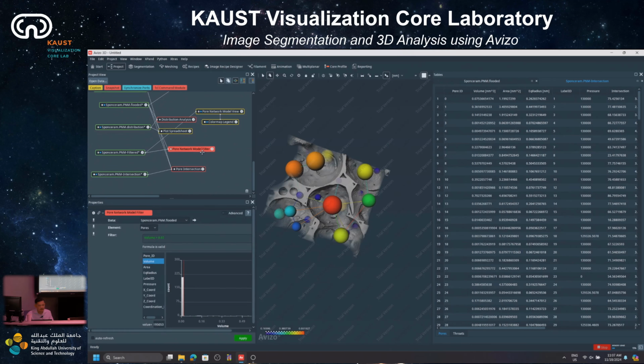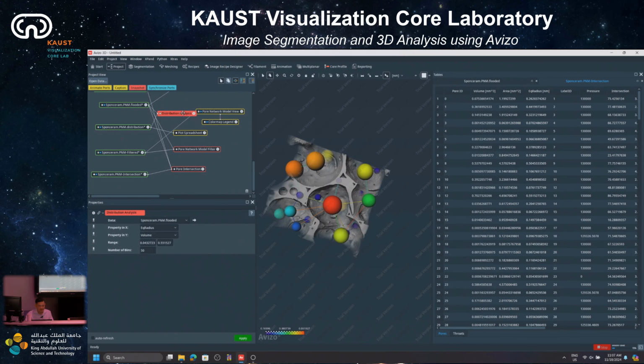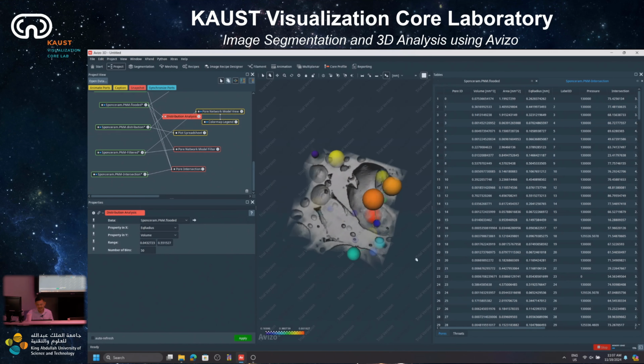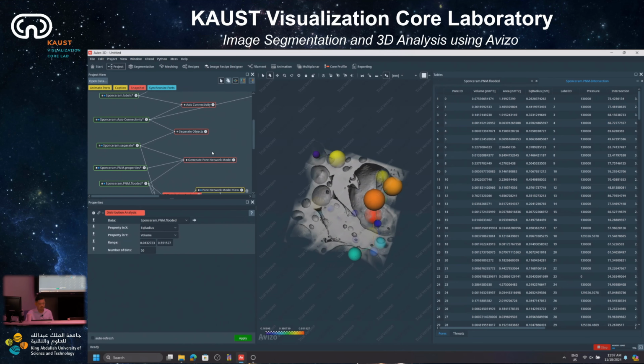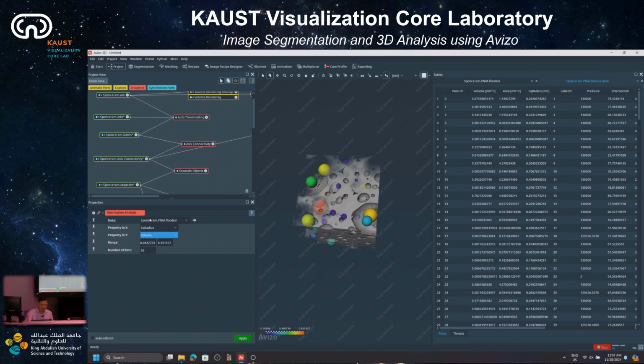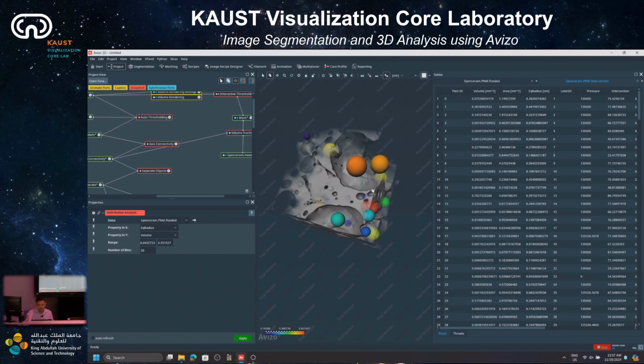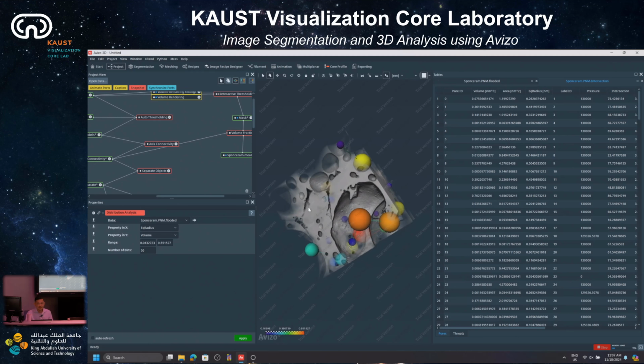Yeah, that's pretty much the pore network model. So you can play around with some parameters to see distribution analysis, to filter them based on size, and to plot the property, calculate volume fraction, and so on. Any question at this point? Yes, exactly. So it's based on the filter again, because you filter first and then you see what this filter is connected to from the previous one before the filter.